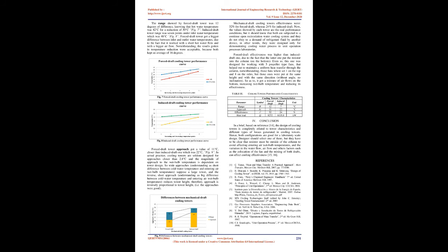Equation 4 is the heat load to remove, Q, in kW, where ml is the water mass flow rate, in kg/s, cpl is the water calorific value, in kJ/kg degree C, and ΔTl is the difference between hot water minus cold water temperature, in degree C.